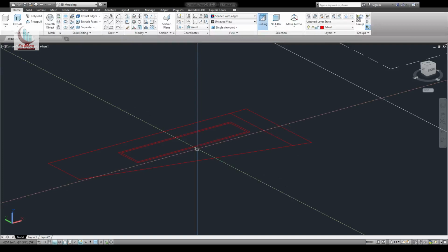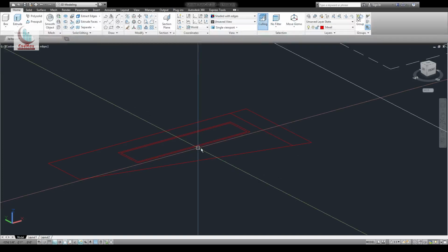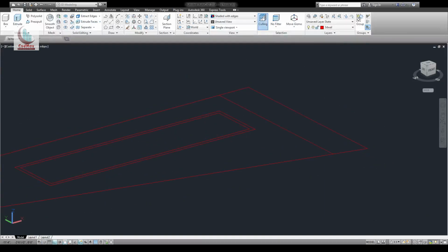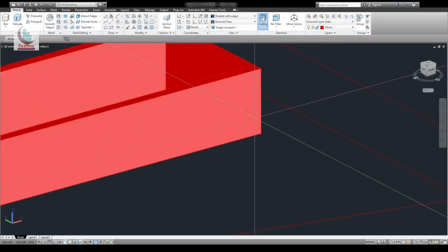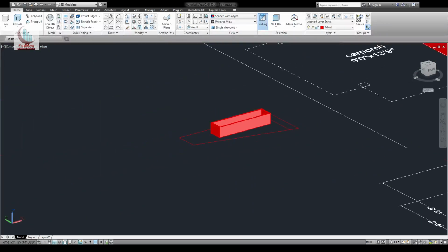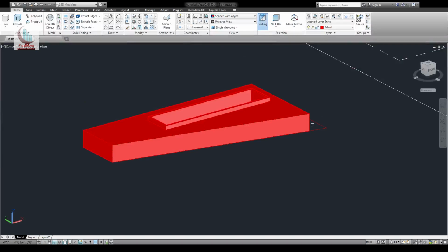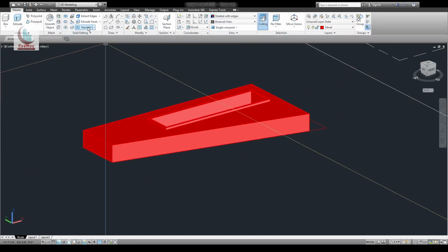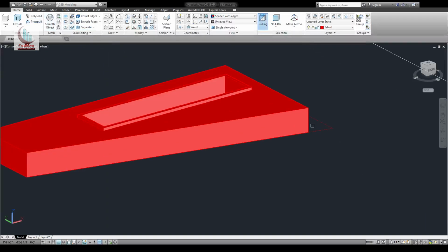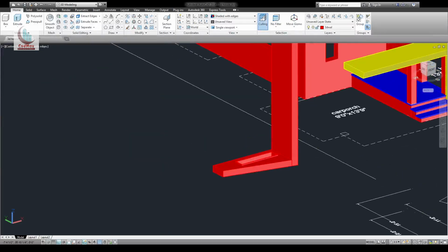Okay. Here you can extrude this. You can use press pull and pull this by 11 inch, this one by 9 inch, move this 1 inch backside, then press pull this by 15 feet 6 inch.